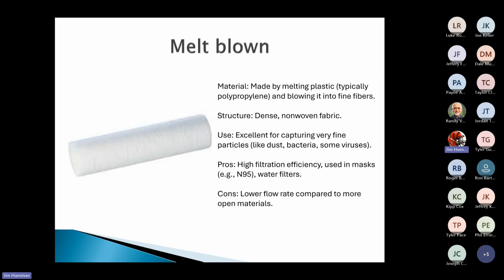The other one is going to be our melt blown. Not a bad filter. I think it has to be kind of designed and placed in the right area. A lot of times what this is, it's a lot of very, very fine fibers wrapped around itself as a giant kind of tube. It does great. It'll actually pick up more material than your pleated filters. But because it's so tight and it's wound so tight on there, it'll get clogged up very, very quickly.